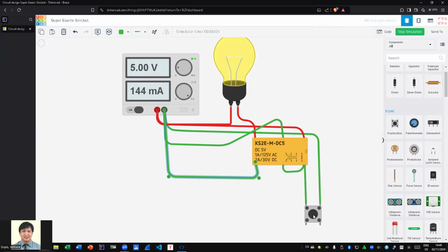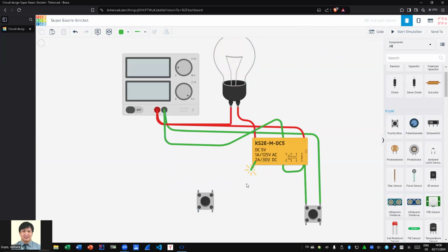When we click it on, we have power going to the coil. When we release the push button, power is still moving from this terminal into the coil to this terminal and moving towards the connection point that we have. The problem now is we need a disruptor. We need something to disrupt the flow of current. So this is where you get another switch and you basically terminate this connection towards this particular switch terminal here.